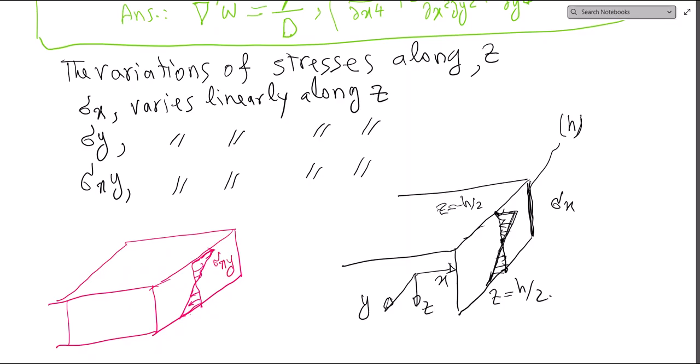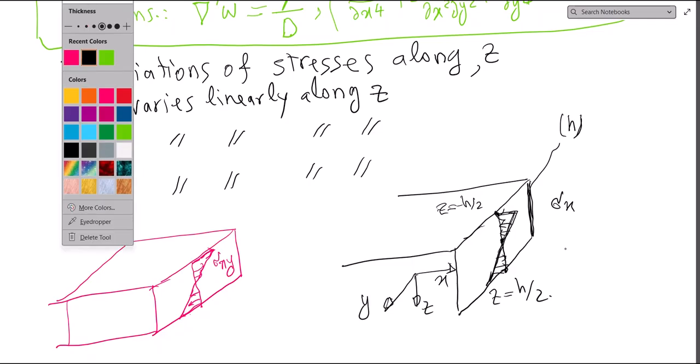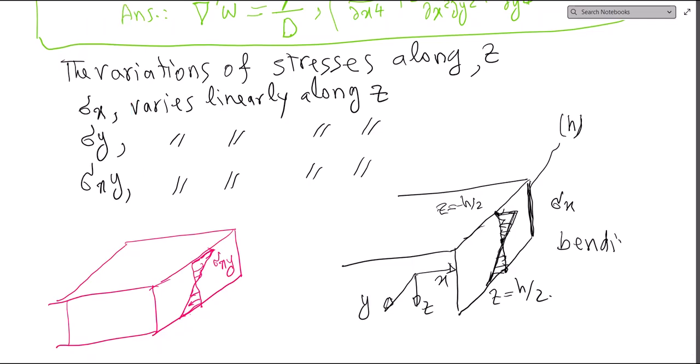So you see here that you will have a twist or rotation due to these stresses, as if they want to twist the plate in the direction. Of course, on the other side we will have the balance of these stresses. But this will create bending. This creates torsion, or if you like, twist. And similarly for the side perpendicular to the y-axis.